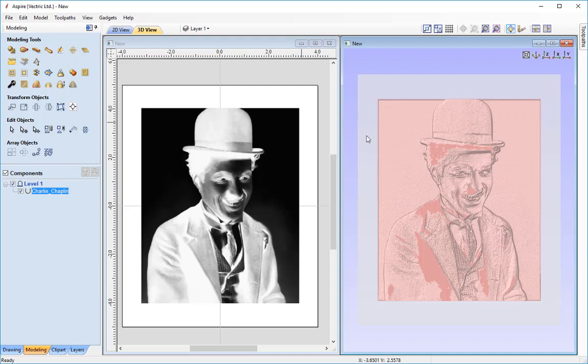The modelling plane is the base where all models are created from. It has 0 thickness, and it's just a reference point to the models we create. We can see the modelling plane now because when we're creating negative models, we create the model below the modelling plane, hence why it appears to be of a translucent look, because we're looking through it. The dark red areas are those that have this equal height to the modelling plane, which is a height of 0. If you just look towards the bottom right, you'll see that the z value reads as 0, and if I go over to the light red areas, you'll notice that that starts to go below 0, like so.